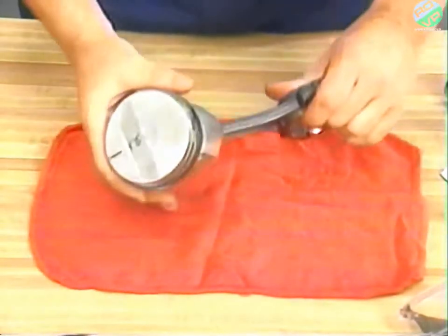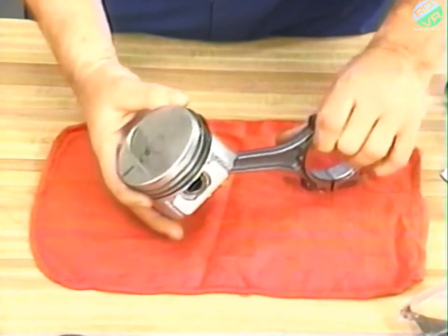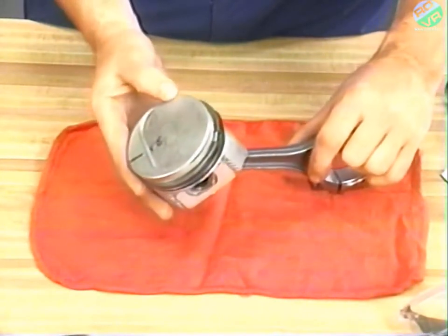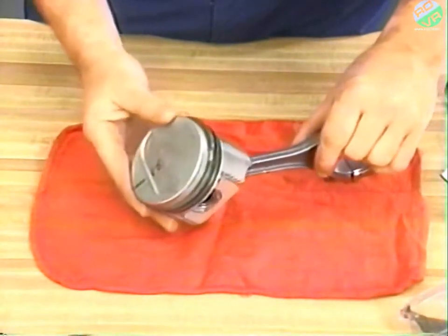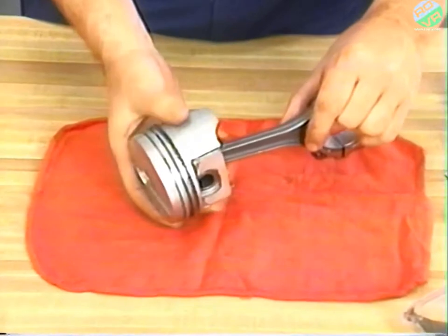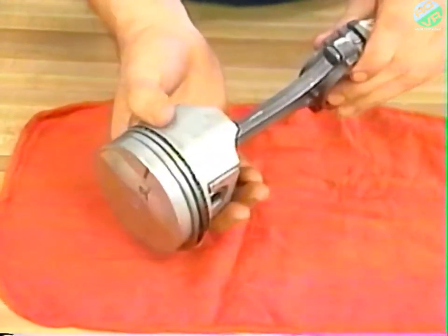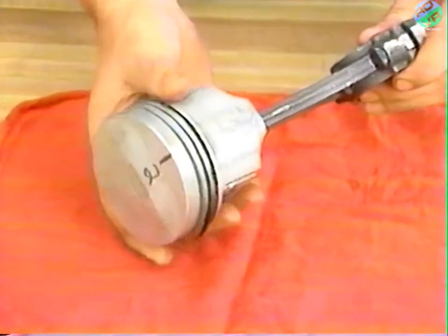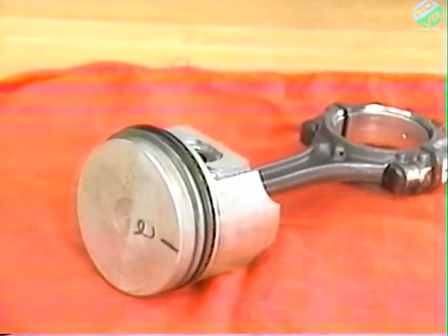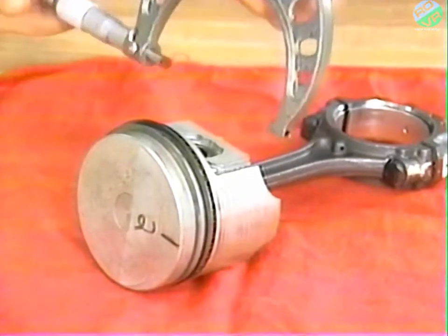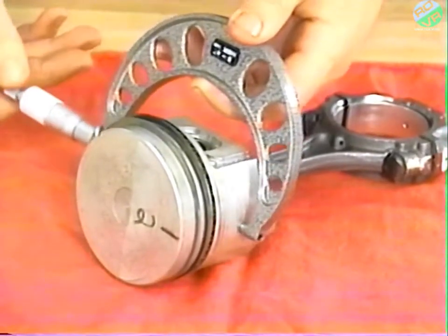Once removed, give the piston a thorough inspection for damage. Check the piston crown for damage caused by broken components. Check the piston skirts and lands for scuffing. Also check for worn or broken rings. Use the measuring procedure shown earlier to size the piston.